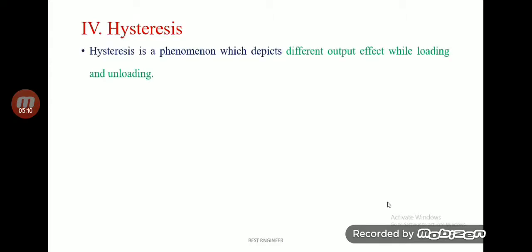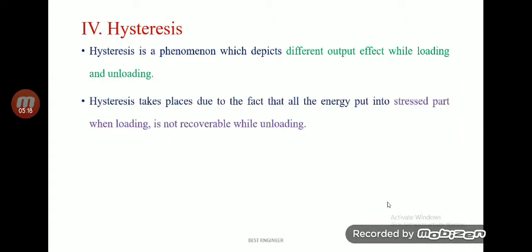Hysteresis is a phenomenon which depicts different output effect while loading and unloading. Hysteresis takes place due to the fact that all energy put into the stressed part while loading is not recoverable while unloading.